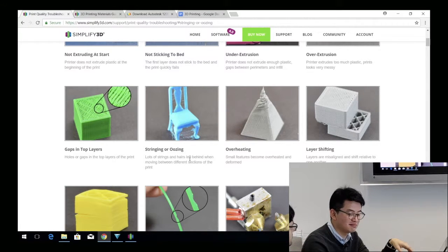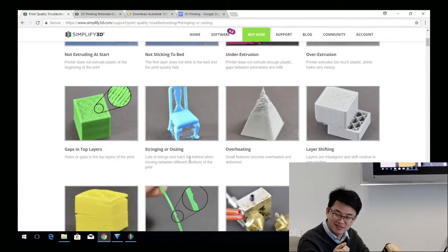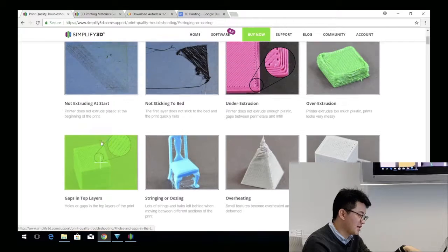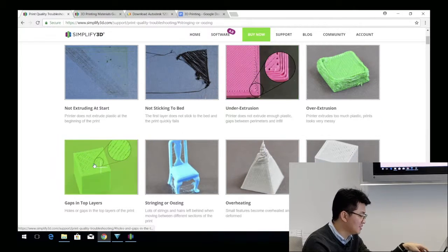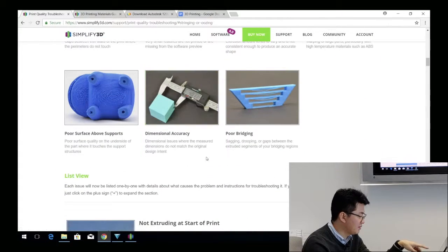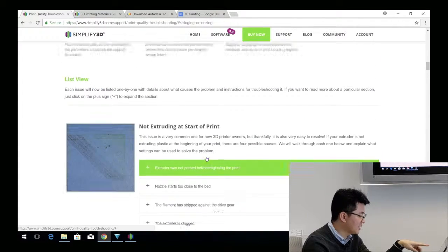Sometimes some designs do not have this issue. If you have it, just remove the strings and use a heat blower or hair dryer to blow them, because they're really thin and melt really quickly, and you cannot see anything. It does not destroy the print itself. So that's another good solution, but I still try not to. The other issues, I ran into all of them at the very beginning, like when the print is all soft. So this is a good place to get some help.